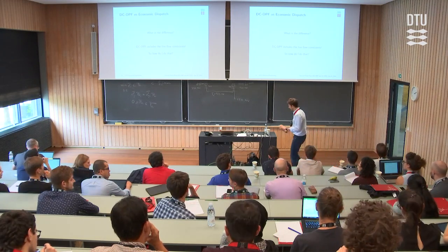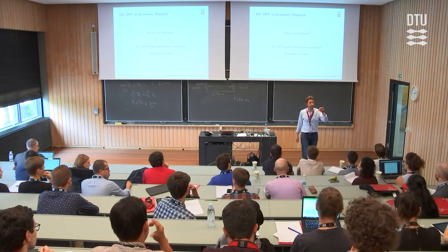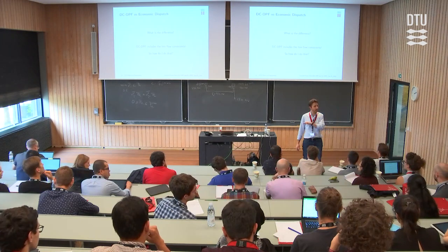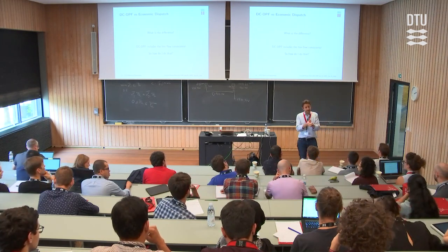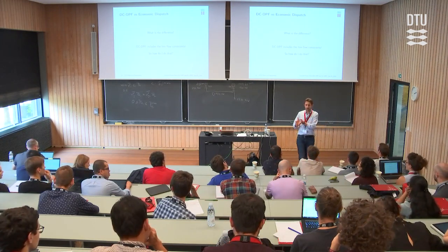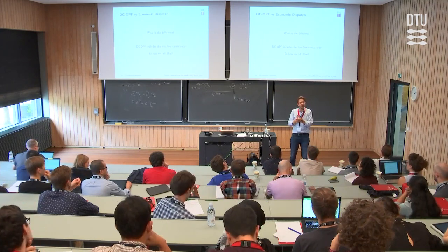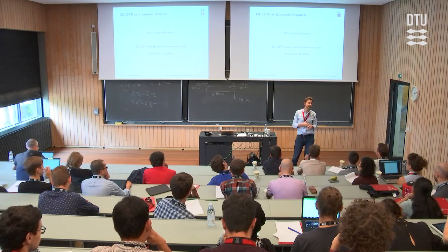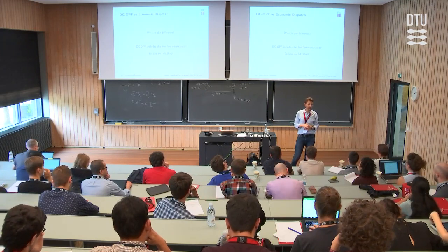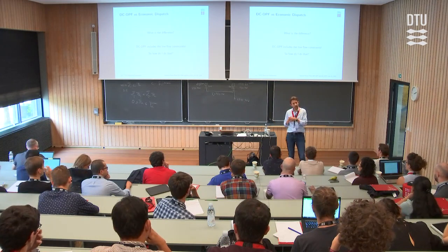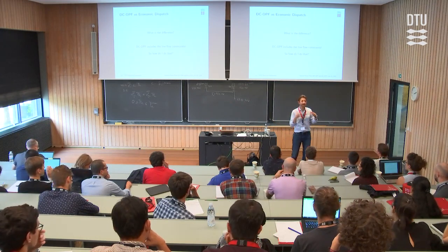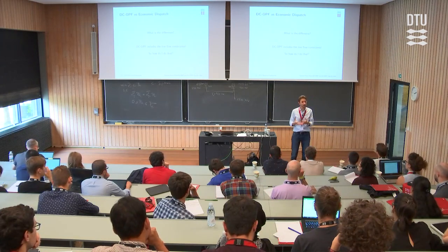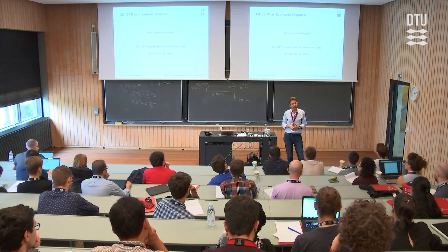Okay. So the price is going to be set from the market. And if you have a power exchange, the price is going to be the same all over your market area. Now, these decisions are actually transferred to the operator, okay? And then the operator is going to see that there are line constraints. I'm sorry, I cannot actually dispatch this generator as much as you thought you can, okay? But this generator is going to get paid and reimbursed for the power that it cannot produce. The operator must pay extra costs for this kind of redispatching.